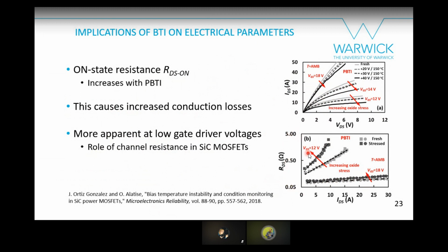Check that this is a logarithmic scale. Also, this is good to explain a question from the first webinar: if the resistance is dependent on the load current, it's just the slope of this. So if you check, when you're driving your device with 18 volts, it's marginally current dependent, so it increases just a bit. If you're going to work from 3, 4 to 10 amps, 15 amps in this range, you can say that the impact of the load current is not high. But if you're driving your device with low voltages, the on-state resistance is very dependent on the load current.